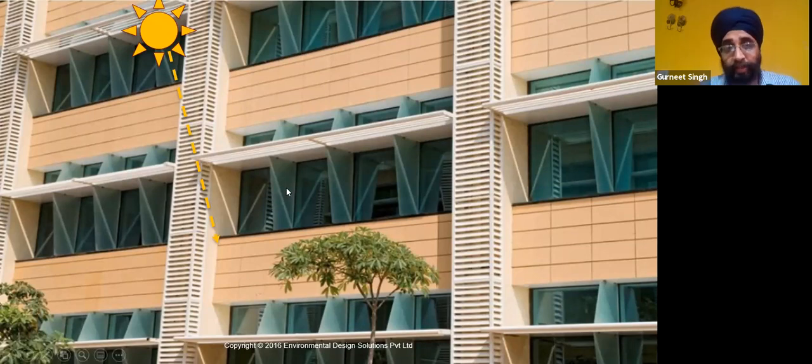Infosys is one of the clients I was talking about, where they have put this as a design criteria that an architect's proposed design should meet. There were three criteria. The first is to ensure that there is no direct solar radiation hitting any workstation. So the architect has to design the building facade in such a way that there is no direct sun coming inside the building or hitting the workstation.